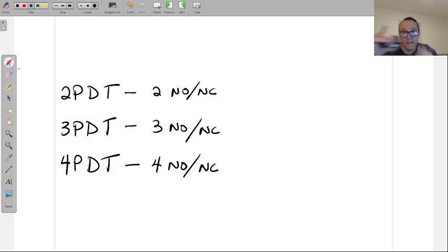And the more physical control relays that you put in, the more auxiliaries, it's just more physical wires. The PLC having the contacts internally removes the use for all of those wire installations, and it really advances the way we can set up a control circuit with minimum hardware, which also leads to less troubleshooting headaches.